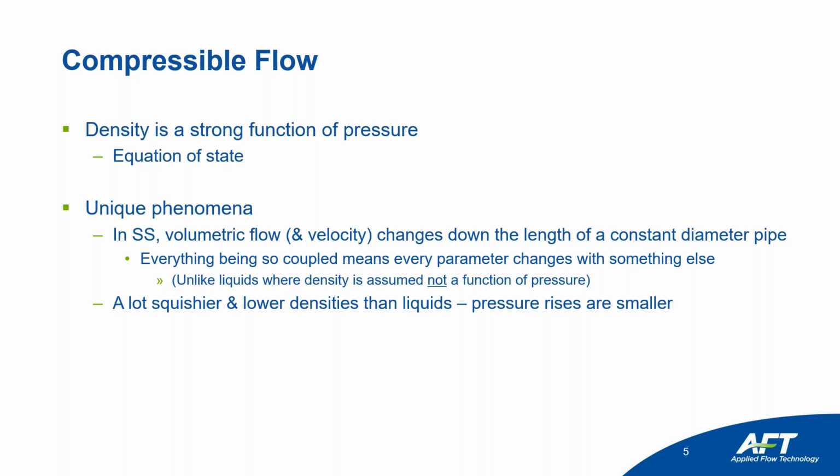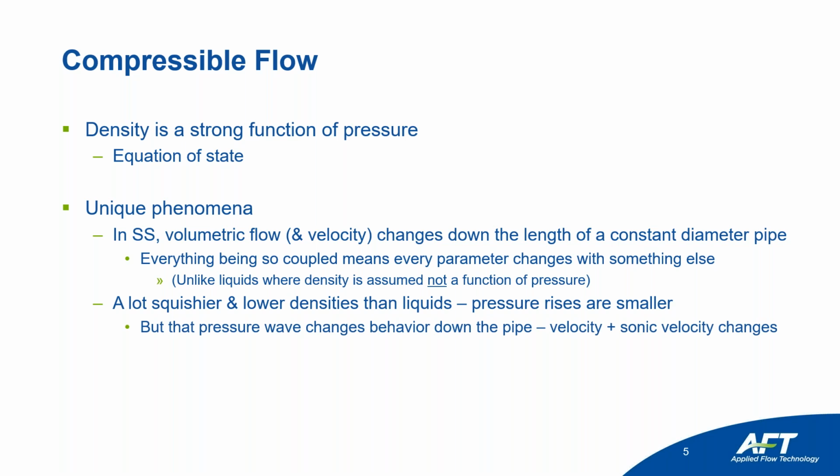Gases, of course, are a lot squishier. They have lower densities than liquids, which means the pressure rises that you'll see from a valve closure are going to be smaller in magnitude, but much more difficult to predict with traditional methods, because the pressure wave behavior is changing down that pipe with the changing velocity we talked about. The sonic velocity is changing because temperature is changing. So this wave front has, I don't want to say unpredictable behavior, because we can predict it with the math behind the software, but it makes it difficult by hand. I would call it prohibitively difficult to analyze by any other means than software.